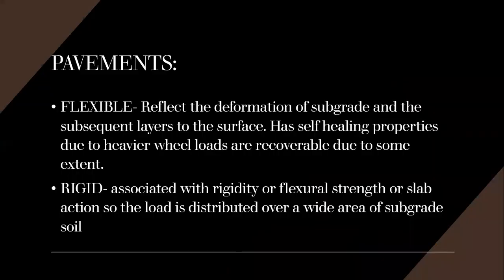Next is the pavements. So, there are two types of pavements, right? The flexible pavement and the rigid pavement. Now, flexible reflects the deformation of subgrade and the subsequent layers to the surface, has self-healing properties, and due to heavier wheel loads, is recoverable to some extent.